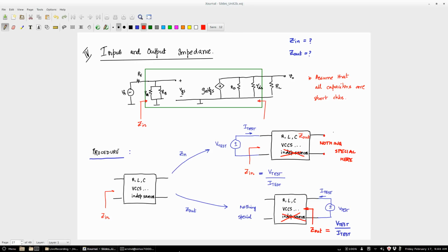So can you tell me, is the input impedance high or low, for this thing? Low? High. It's a high input impedance. In the limit of RA parallel RB being infinity, being very large, you will have a good input impedance, which is what you want.